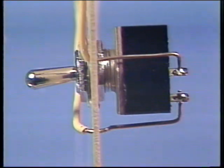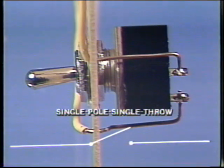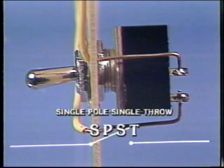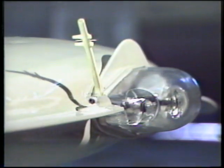Current may be controlled in a circuit by the use of a switch. A switch that opens or closes only one circuit and has only two connections is called a single pole, single throw, or SPST switch. This is a simple on-off type switch, such as that used for controlling aircraft position lights.